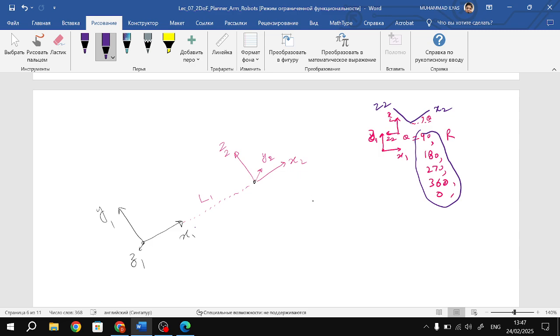Just about the x-axis. Because of these directions, they have some relationship of 180, 90, 360, or 270 degrees. In this situation, you calculate the rotation matrix between frame 2 and frame 1 by considering it like this. x1 is in the same direction as x2. We got this x1, this is x2, no problem.